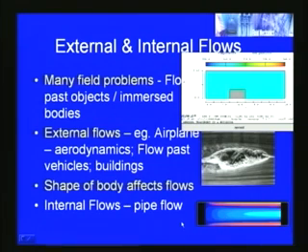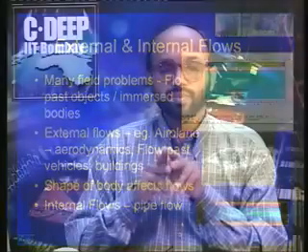So, like this, there can be a number of examples where the fluid may be flowing through an internal flow, like in the case of pipe flow, or the fluid passing over immersed bodies or past objects, which is external flow. In all these cases a boundary layer is created, and in most practical fluid flow problems we have to deal with this boundary layer.